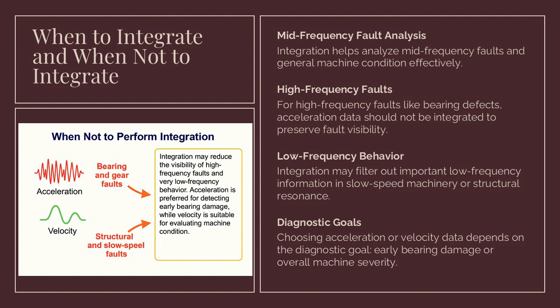Analysts should also consider the diagnostic goal. If the objective is to detect early bearing damage, acceleration is preferred. If the goal is to assess overall machine severity, velocity is ideal. Understanding these nuances ensures that integration enhances rather than compromises diagnostic accuracy.